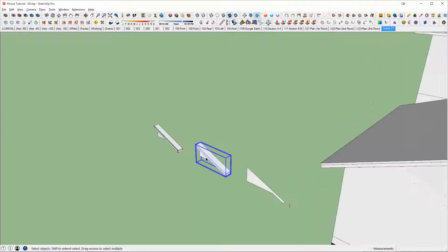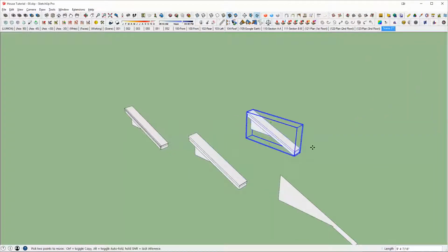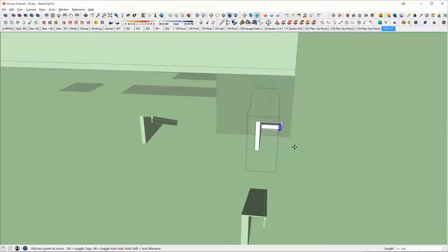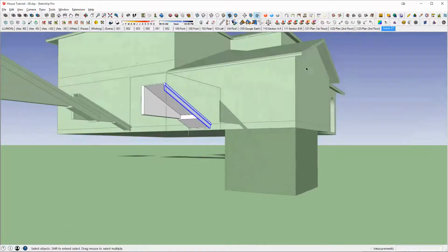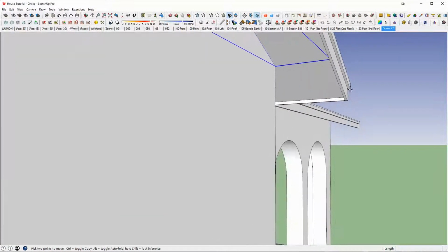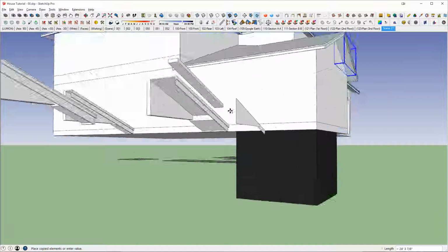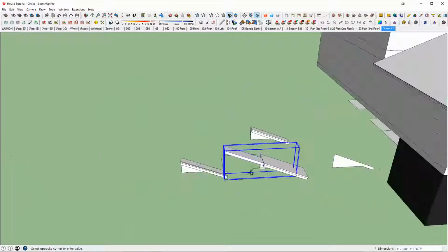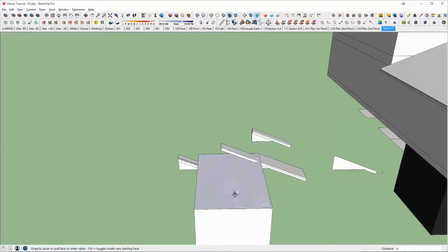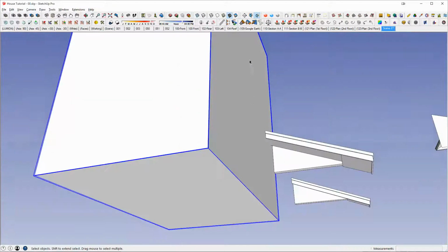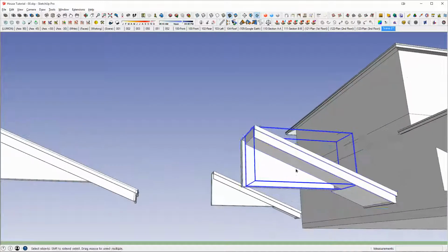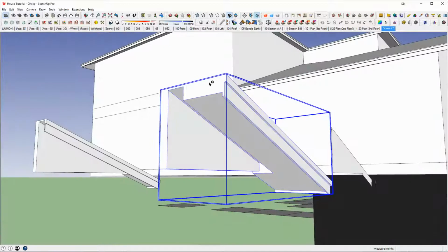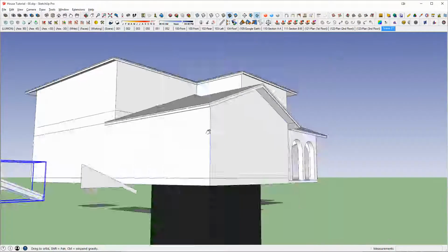So with that in mind, I know I want to re-edit my jig, so maybe I want to keep my 0 overhang version as well as create my 18-inch overhang version, just so we don't have to keep re-editing the roof. So I come back in here and put that piece there. And you can see if I create what I call my cutting box, turn that into a solid, use my solid cutting command, and then Alt-C to join, there you go. So there's my soffit built back into my jig piece.